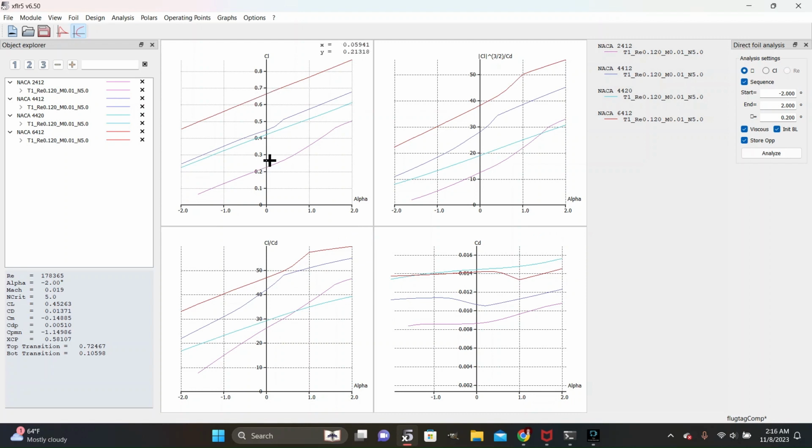So yeah, we get a far greater advantage in lift than cost we do in drag if you compare the ratios for both these powers. I haven't run a MATLAB analysis yet on optimizing it. That will be shown later. This is more a basic approach. So going off that, I like the 6412 for my analysis.